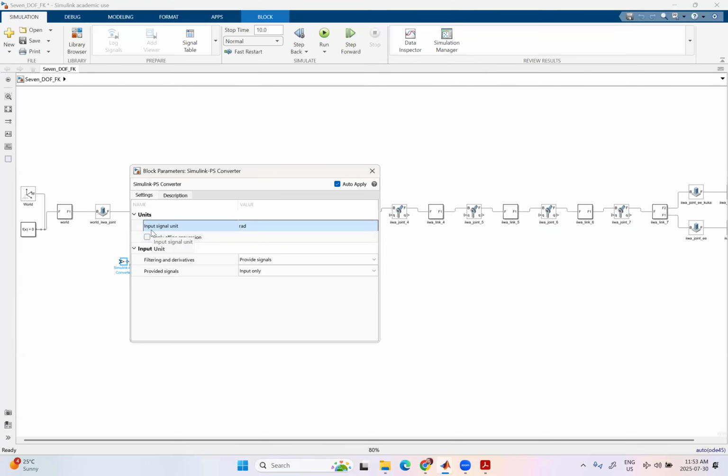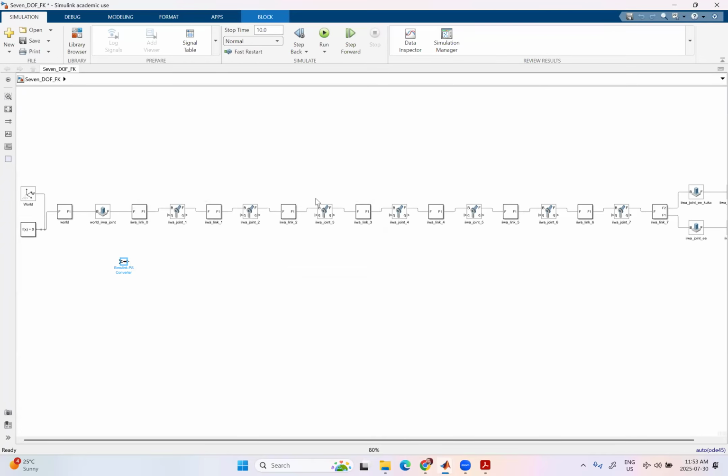And then another thing to consider is input handling, because don't forget, we need to also calculate acceleration, right? We need to calculate torque information, because torque is not something that we want to feed an actuator with. We need to calculate it on the back end. So for that, we would have to use a second order filtering so that we are able to calculate torque. There is a philosophy behind it, but I'm going to skip that. That is what I need to do for this part.